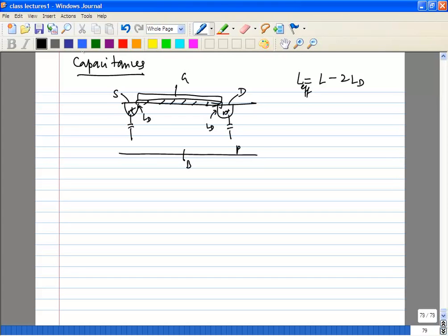Then let's say you have a channel, and in this case it's in saturation. Remember that this is an N-type channel and this is a P-type substrate, so there is going to be a depletion region between the two. So you also have a channel to bulk capacitance.